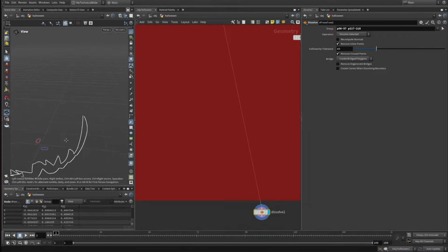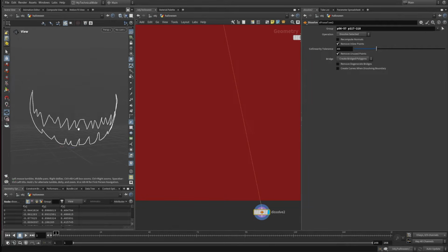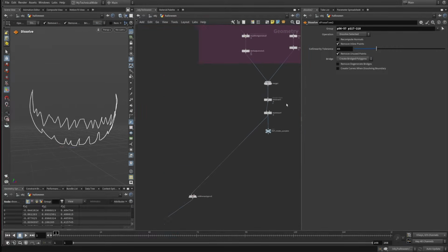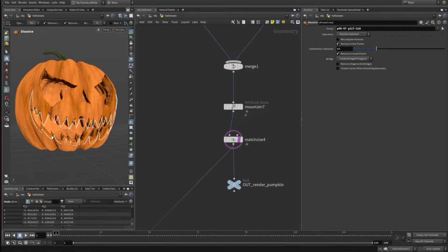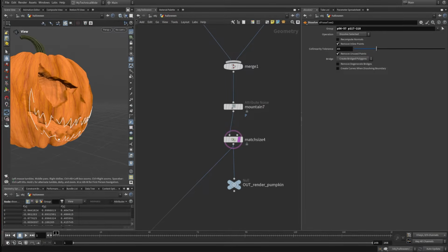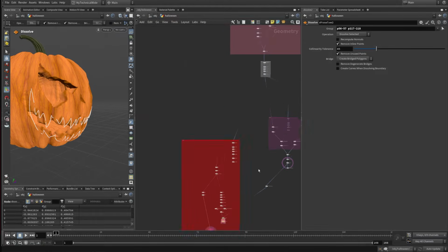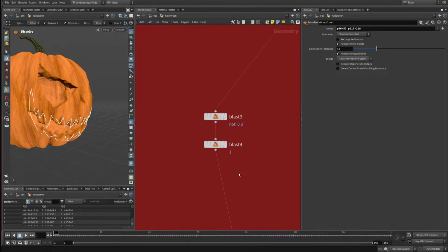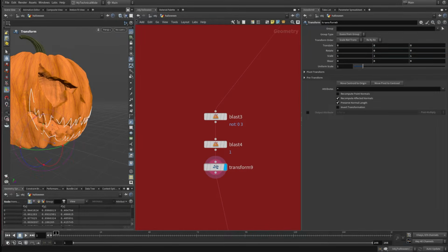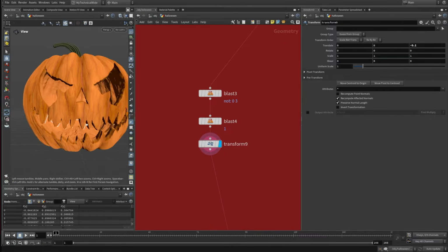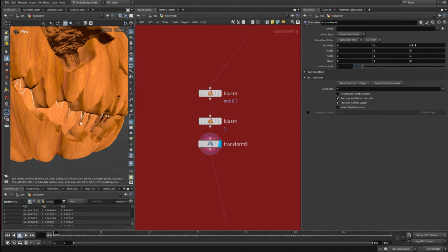So now we can just select the top part and the bottom part and move it freely to align better, right? Because it's not, again, it's not very ideal how it is aligned. So let's globally transform both parts and then we will align it a bit better. So let's put down transform, and I'm going to push it back minus 0.1. Okay, and we just want to move the top part a bit more up. Okay, so we can do it simply with the edit node.